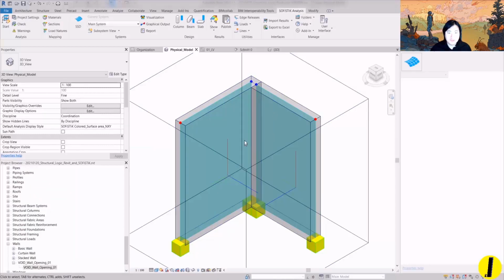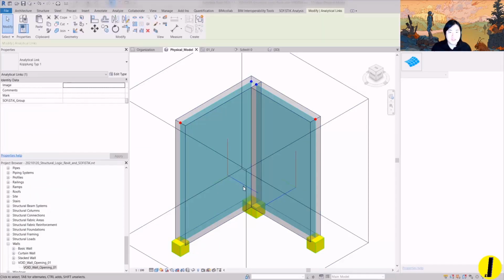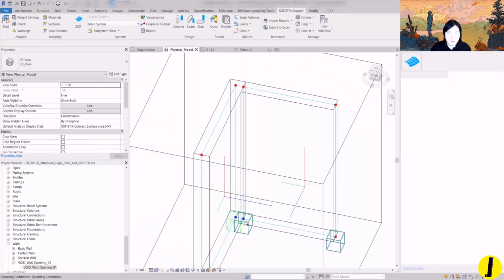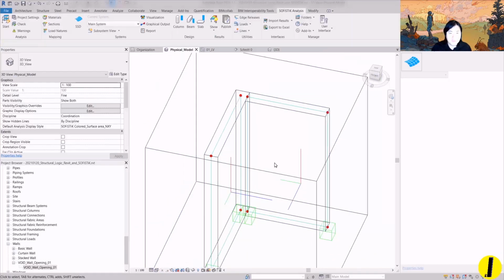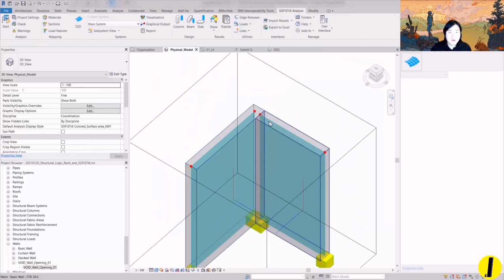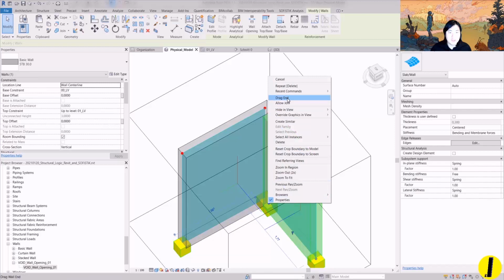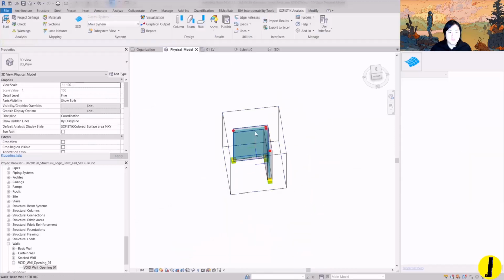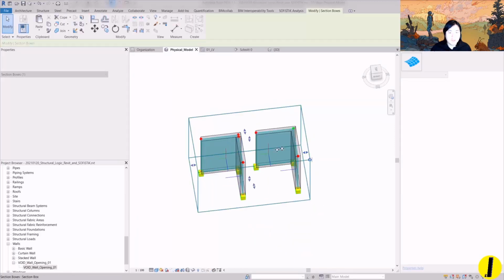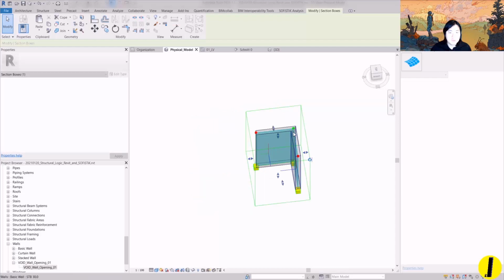So in this exercise it is not very good for the wall joint. Just keep in mind that perhaps using this disallow join option is not good for the structural analytical model of the wall. Next, so I think that's clear. Let's move on to the next.